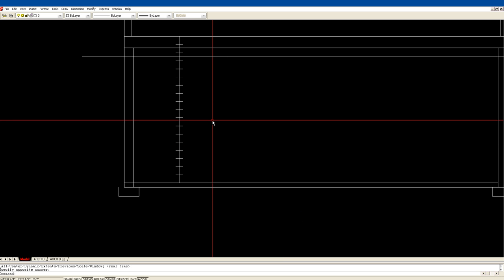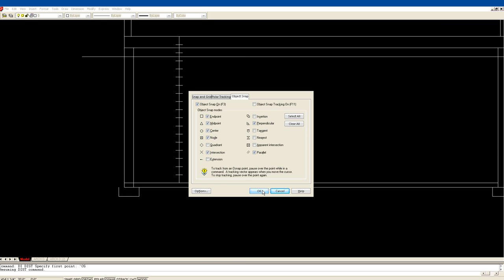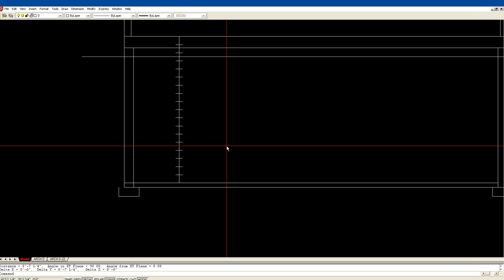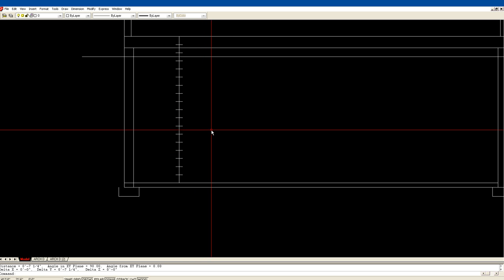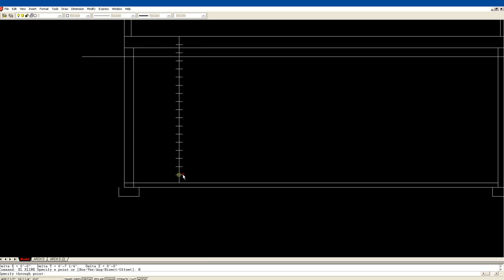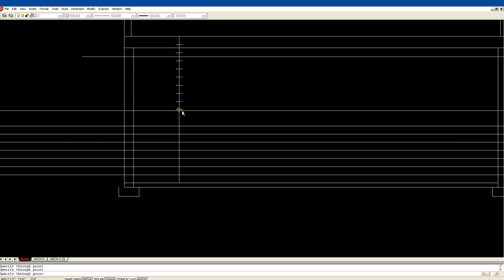Now, we did the calculation on a calculator. Let's just check it here. So the distance from, oh, I don't have my O-snap set up. I'm just going to go apostrophe OS for O-snaps, and I'm going to set up on node. Now the distance from that node to that node is 7 1/4 inches. We figured 7.22. Well, AutoCAD is saying that the way we're set up, 7 1/4 inches is what you're going to divide these by. So you've got 18 times. We're just going to draw X lines, and this time we're going to draw horizontal, and we're just going to pick on these nodes. Oops.